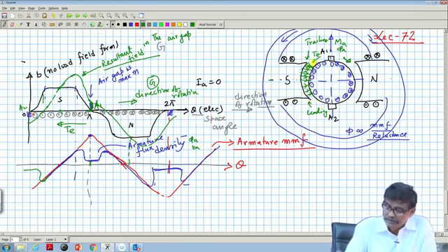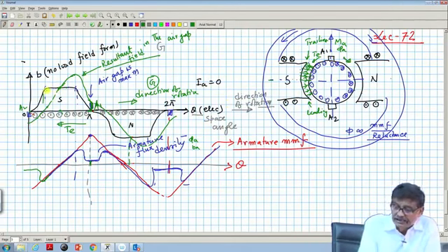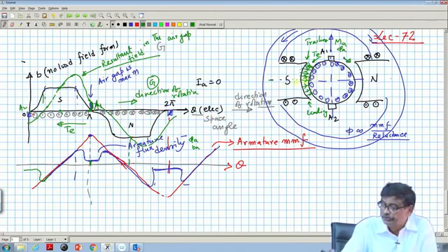So, that will be like this, and it will be here. This height is same as this armature flux along the quadrature axis. So, it is only distortion, that is the main issue here. There is no direct component of armature MMF which really negates in direct opposition to the existing stator field. Okay? That is the whole idea.